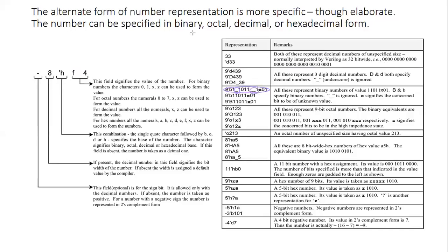It is just like, if I take an example of a 2:4 decoder with enable signal. Let me take enable as one input and x[1:0] as the other input. Now when I write the test bench for this, I will write it as enable comma x, and this can be written as 3'b, and the value of enable, active high enable, will be 1.